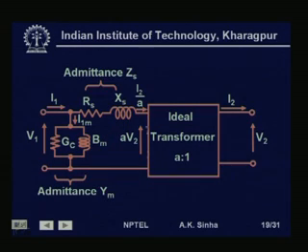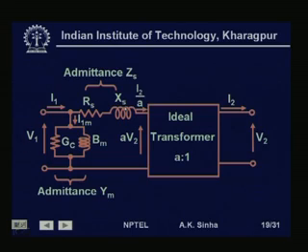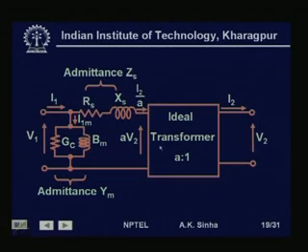Then our equivalent circuit becomes like this, because we can now combine RS1 and RS2 and XS1 and XS2. So, we can write them as RS plus j XS, where RS is equal to RS1 plus RS2 and XS is equal to XS1 plus XS2. So, this is now the equivalent circuit, which represents the magnetization current, the core losses, the winding losses and the leakage flux. So, this is an equivalent circuit for a physical transformer.